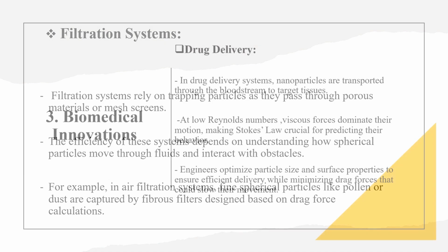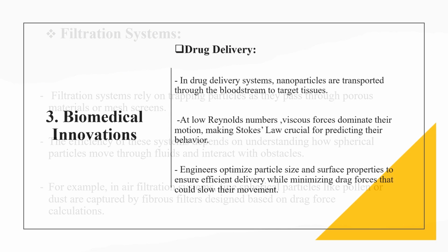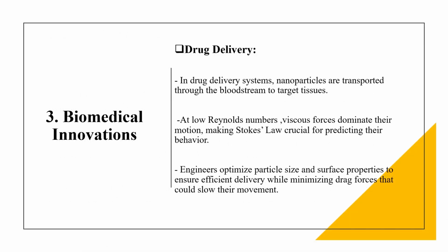Finally, let's look at some biomedical innovations where understanding the flow of fluid past spherical particles has a direct impact on improving medical treatments and technologies. In drug delivery systems, nanoparticles are often designed as spheres to transport medication through the bloodstream to target tissue. At the small scale of nanoparticles, viscous forces dominate the flow behavior, making Stokes' law essential for predicting their motion.